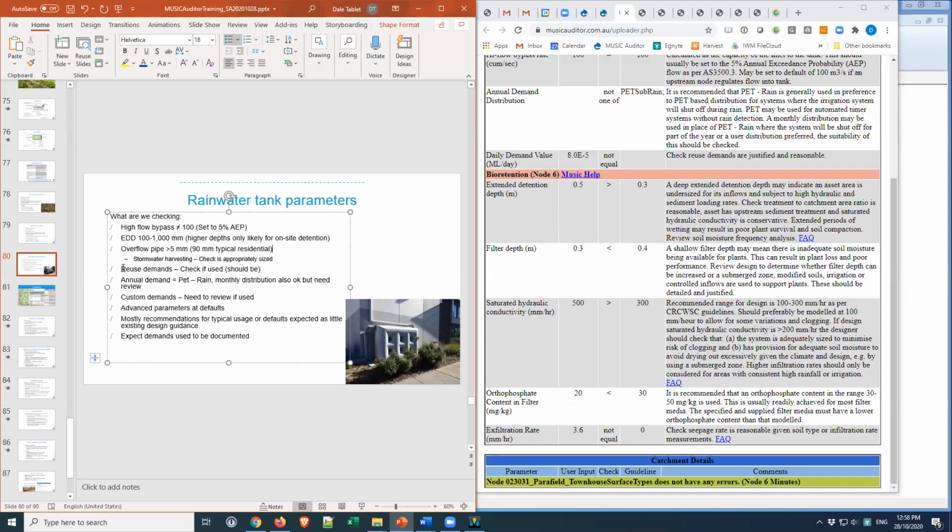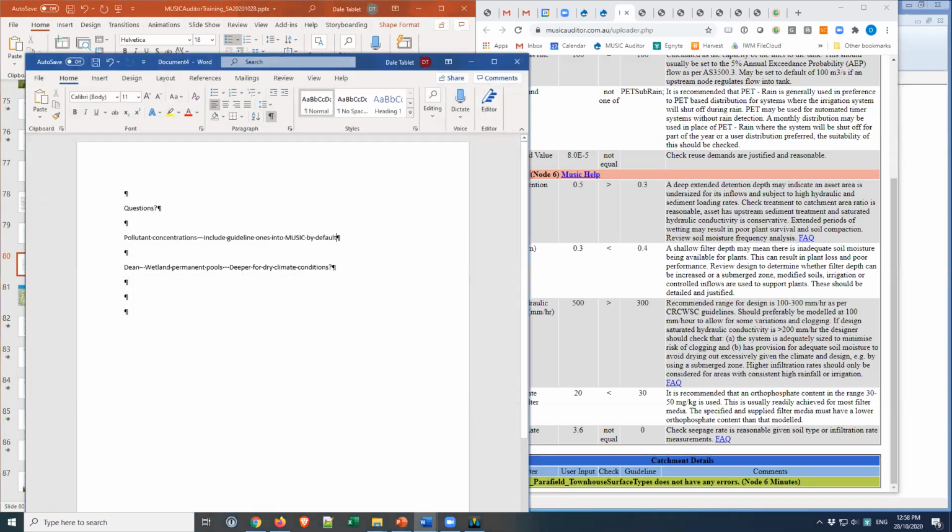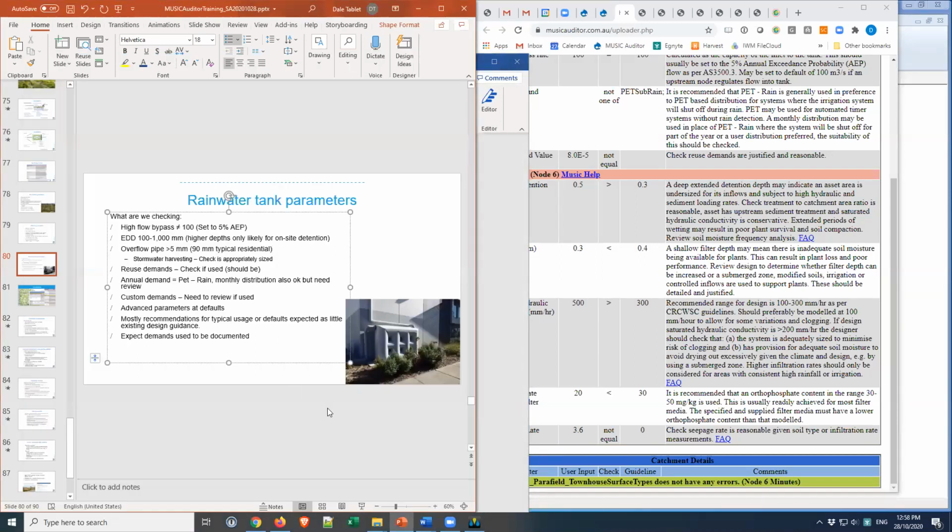Dale, can I ask a question there? Yep. So we've had a bit of this with our Insight Water tool, a bit of discussion about that. Sure. With the orifice size. Yep. And there's been a bit of debate here that councils generally won't let anyone have anything less than 20 mil. Yeah, okay. For blockages. Yeah. So I'm just flagging, maybe we need to have a chat about that. Yeah, okay. If that's the case, it might be worth us revising the guidelines to check a minimum of 20 mil in that case. Yeah, all right, I'll note that. Cheers. Yep, thanks, that's good.